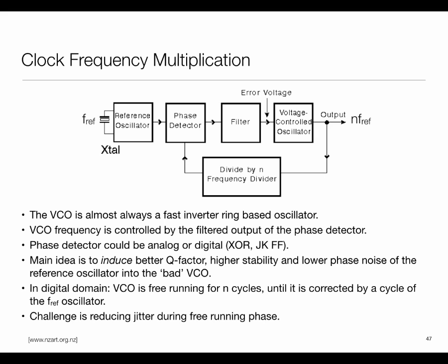Almost every modern processor has a PLL, so that you can internally generate a high frequency clock. You can internally generate all those other weird frequencies needed for things like USB and other types of interfaces, even though you may have a single source out here. And the nice thing is that all these clocks you're generating are nicely synchronized because they all come from the same source. If you had different clock sources for each of them, your USB frequency would not be synchronized. The clock would not exactly follow the clock of the processor, and all sorts of bad things can begin to happen. So PLLs are a crucial part of these systems.